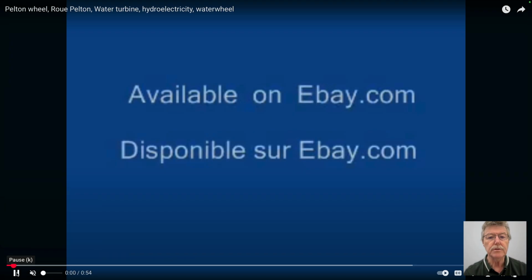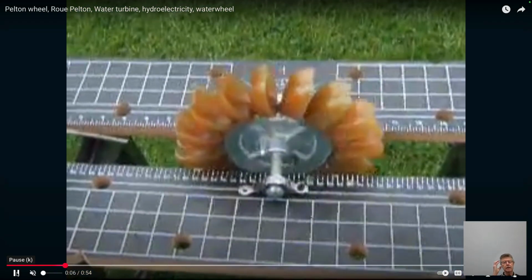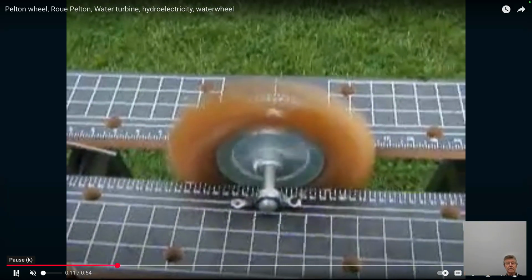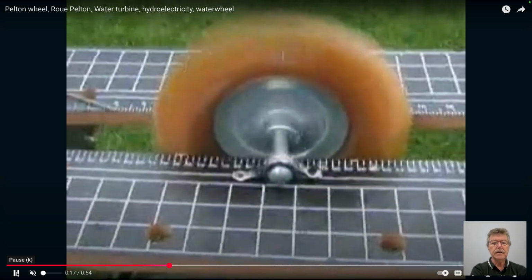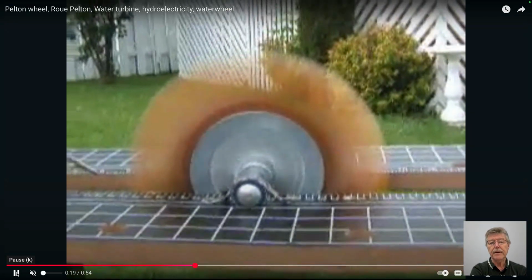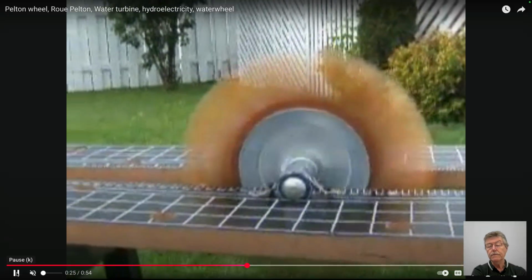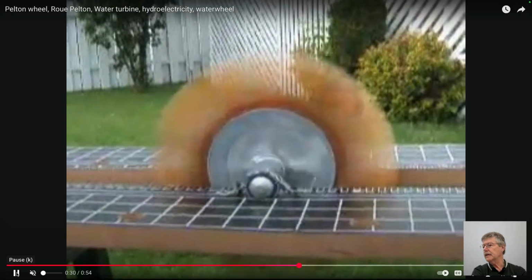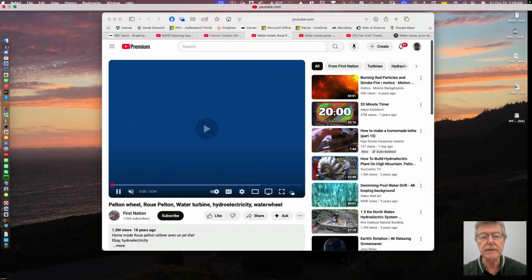system, and we've seen this before, but this is kind of what we'll talk about today, and that is that you could imagine each of these little cups being the vane that we had going across the floor horizontally, and that's how we'll try and treat it. It's the easiest way to treat it. But you see it's taking a velocity to the left-hand side. It's coming out of this hose at Vs, V static, and it's causing the vane to move at some velocity of the control surface and some incoming velocity into each of the cups, W, which we talked about. So that's kind of what we'll talk about today.